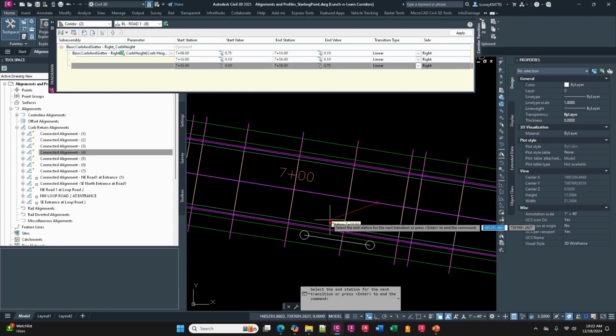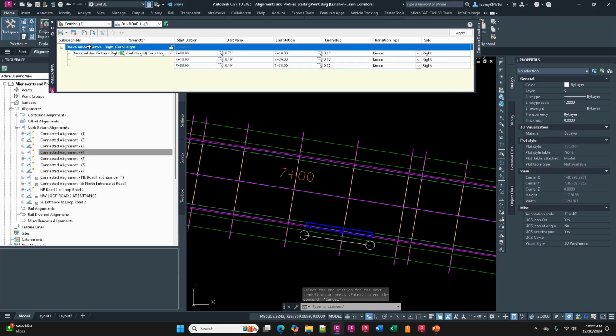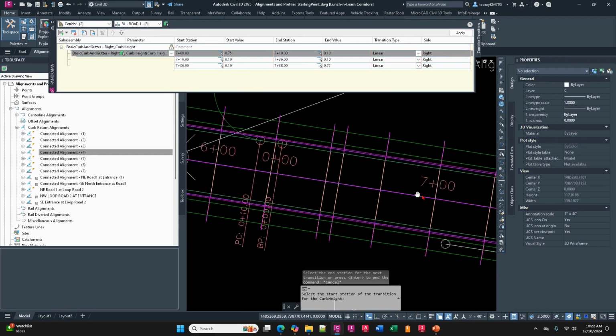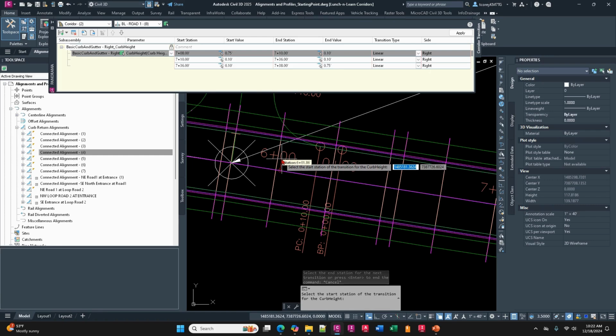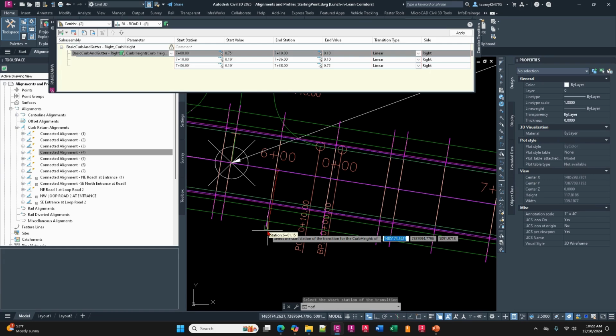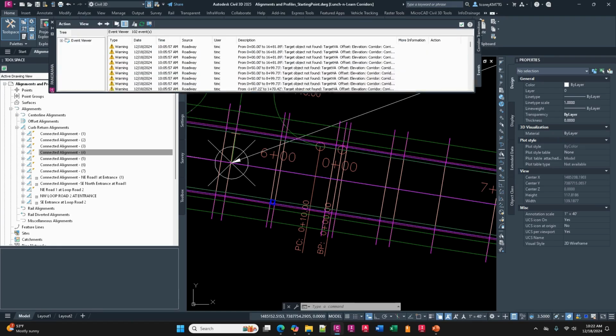Okay. Hit escape there. Now you can take this whole setup here and lock it together. So I could say, well, that starting point 708, actually, I want to move that up here to 600. And I can just snap if I want. Where's my E for endpoint? And you see everything else adjusted. So now if I apply, that transition is here.